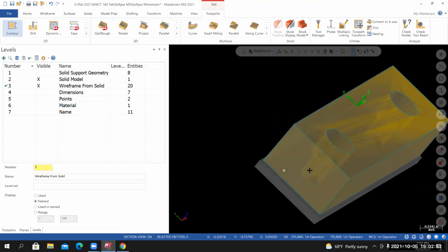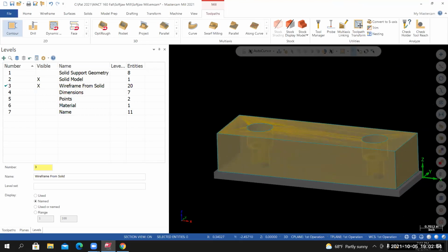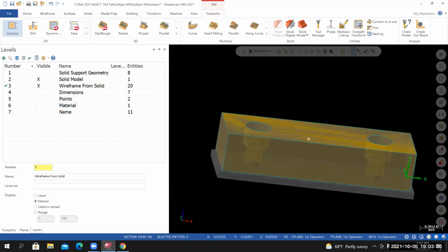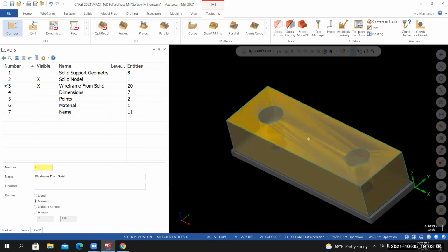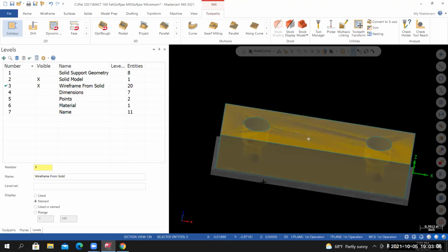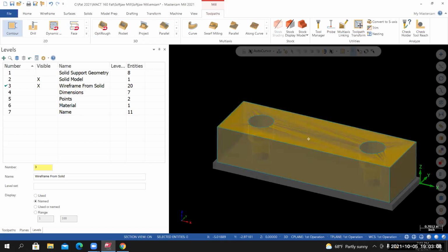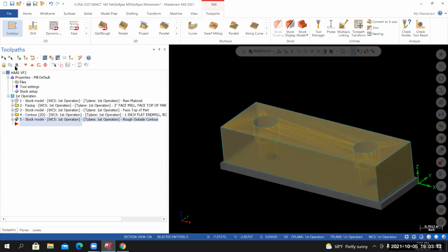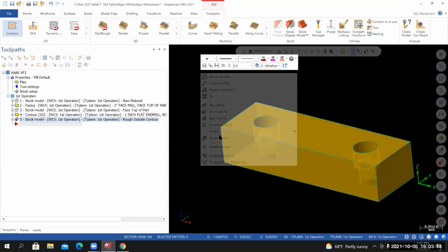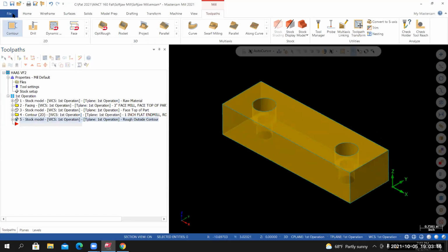And we just need to be careful how deep we send the tool so that we don't machine into the hard jaws, damaging the hard jaws and more than likely damaging the cutting tool. So this is what the part looks like after the first two toolpaths. So from here, I'll toggle out the visibility of that stock model and I'll save my work.